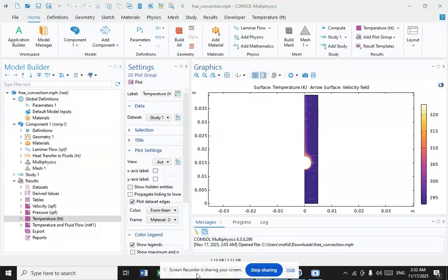Different behavior can be observed between these two experiments. Although the temperature fluctuations presented by Nagano in 1988 are larger than the streamwise normal stress, it is vice versa in Persson and Karlsson's 1996 work. However, the location of the peak remains in close agreement. Natural convection boundary layers have also been studied using DNS or LES. However, most of the studies involve fluid either in cavities or differentially heated channels.